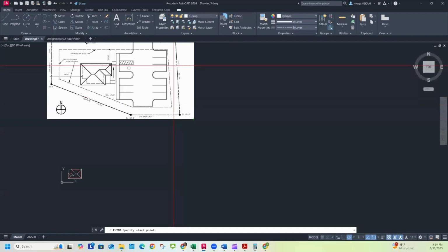So I'll go ahead and do one with polar coordinates, and I'll do the other one with the rotate command. So if I'm starting with this line here, and I want it to go 115 feet north from this start point, so I'm going up 115 feet north, and it needs to be at an angle of 3 degrees and 15 minutes west.